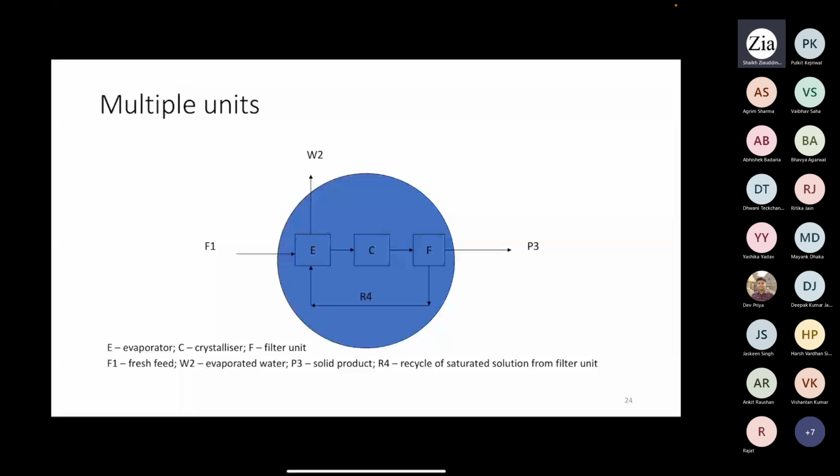In some cases, you will see we deliberately use some gases which also have some disinfection properties, like sulfur dioxide. Deliberately, we will use some sulfur dioxide in the system to prevent spoilage of the material. And then we will do further size reduction or separation. And then finally, after getting the desired quality of raw material, you will put it to the production unit.